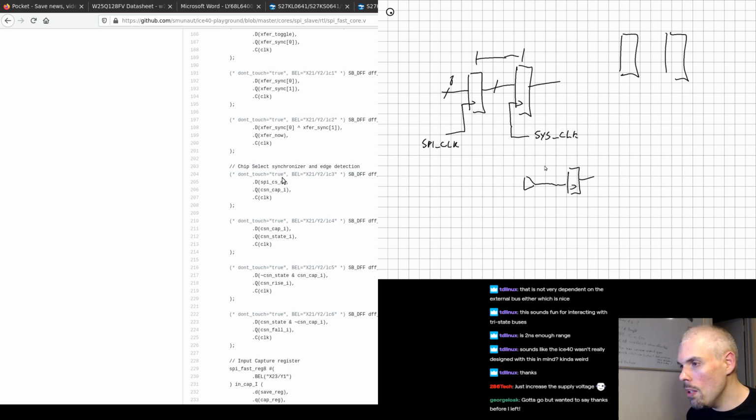And the only way I could guarantee that this design would be stable and work all the time and work reliably, independently of the random seed that NextPNR chose and whatever placement it made, is to make sure that all my input and output registers are locked at a specific site inside the FPGA that doesn't move relative to the IO.